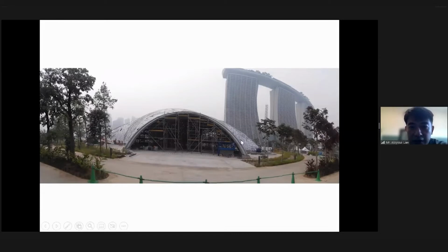And this is the pavilion during construction. So as I mentioned, essentially this is one arch and there's another arch here. So whatever is behind here, that's the actual grid shell. We needed all this construction staging to ensure that the middle portion of the pavilion is supported while the arches are constructed in place.